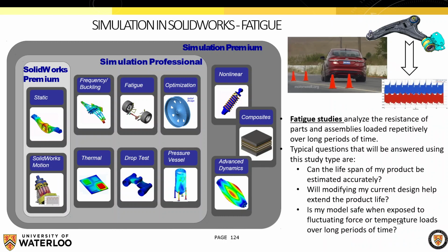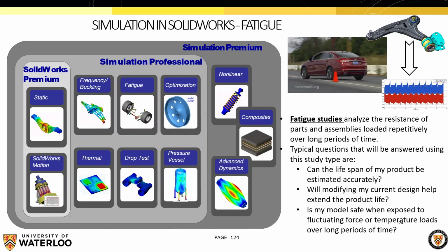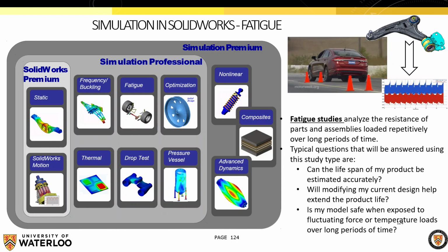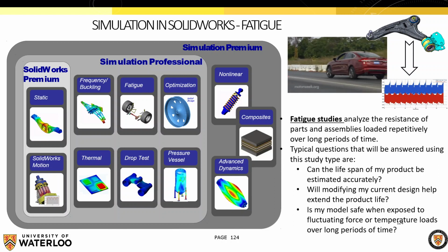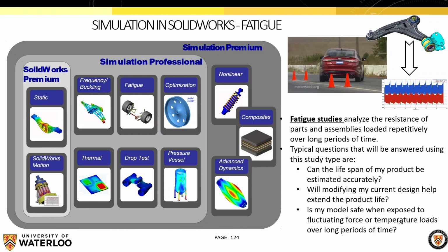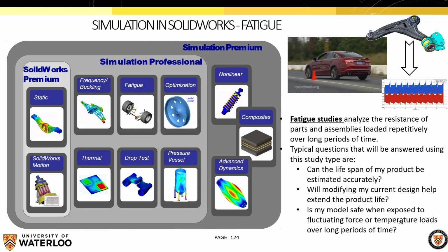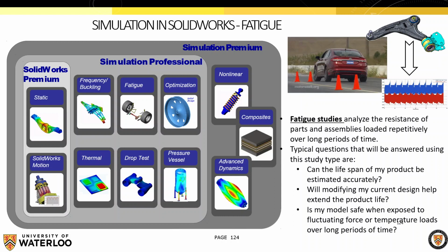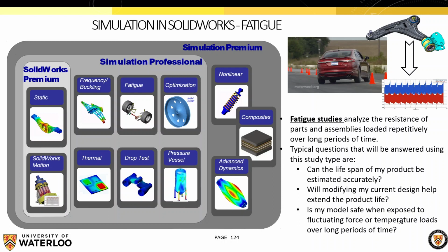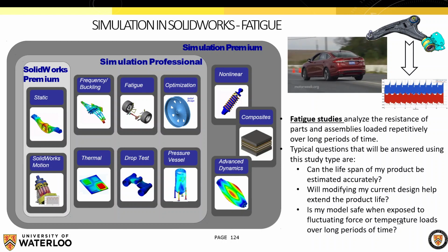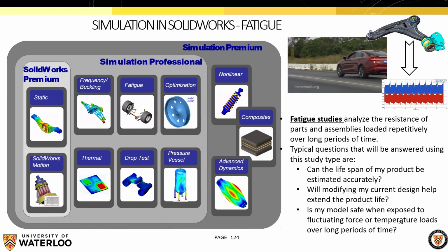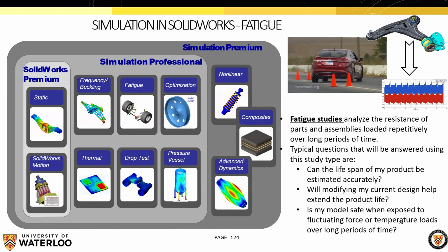Fatigue is something that a lot of people don't really concern themselves with, but my last 10 years at the university have been consumed by this one topic. And it's very important because it analyzes the resistance of a part or an assembly or anything really that is loaded repetitively over a long period of time. So this is a cyclic loading event where you have, let's say in this case, a car that's driving left and right on this proving ground type scenario, and you're gathering all of these different forces and moments and all these components that are deforming something. Not to the point where it fails immediately, but you're accumulating damage slowly, slowly, slowly.